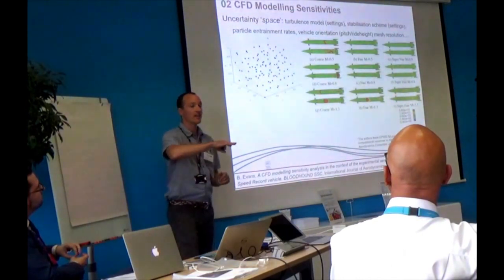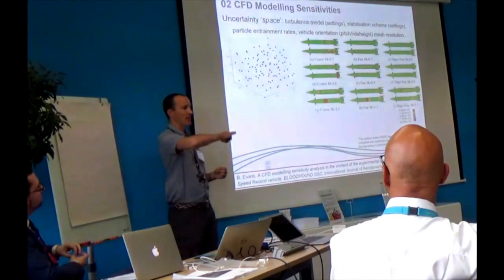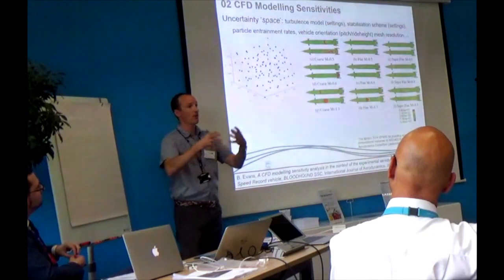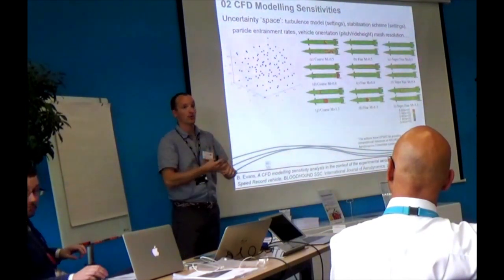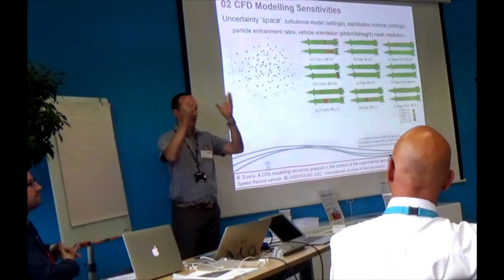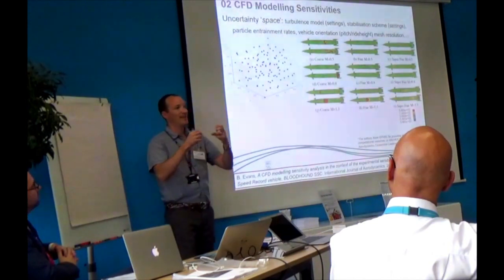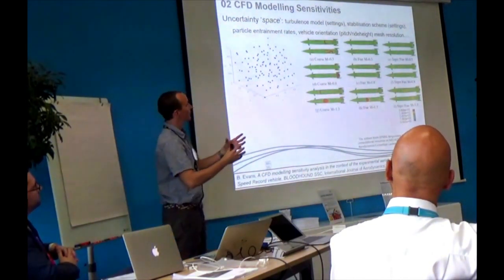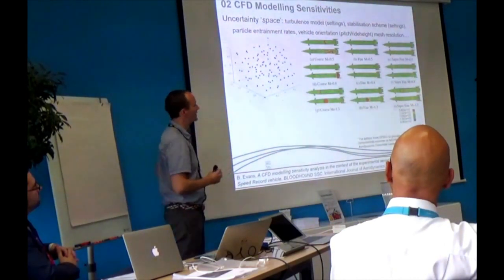The orientation of the vehicle: all of the design work was done with the vehicle set at some standard ride height and pitch configuration. Basically, we were running the models, changing the geometry to answer questions like, is that better or worse? Has the drag gone up or has it gone down? Has the lift gone up or has it gone down? Now we're starting to think more, in quantitative terms, about how accurate these models are, and to what extent pitch and ride height affect these solutions.